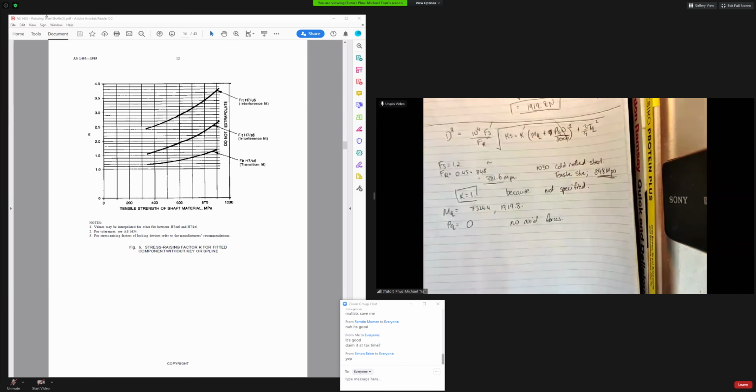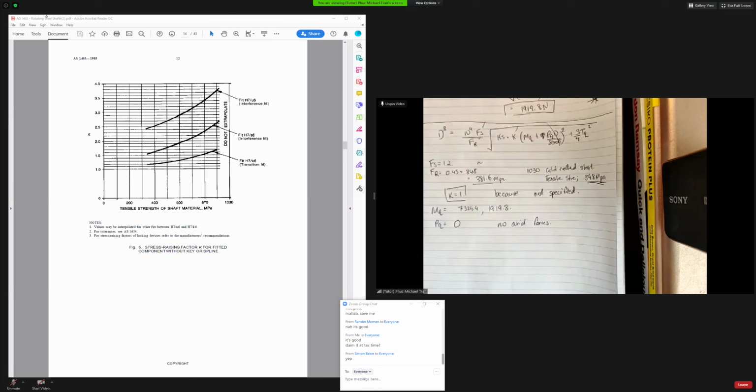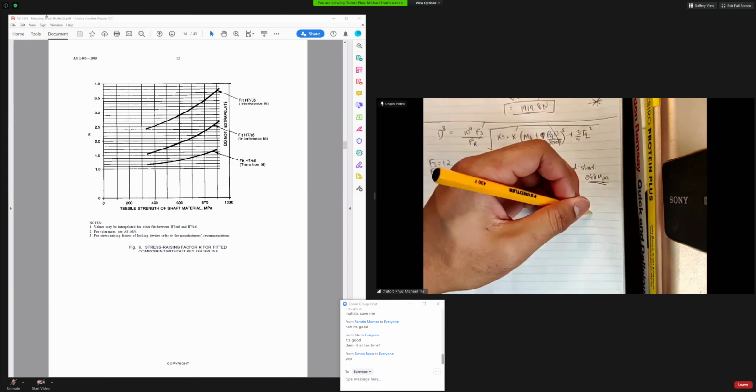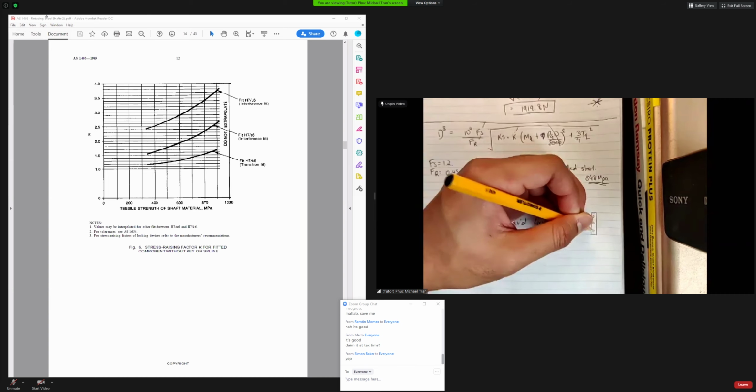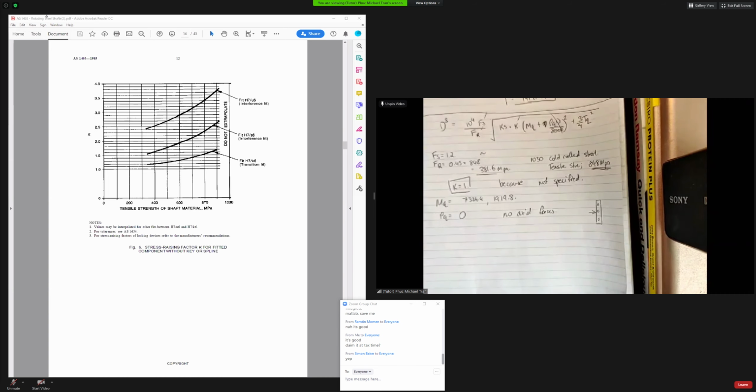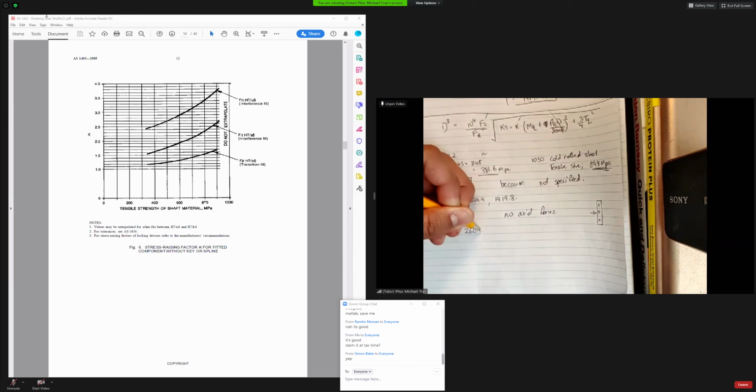You would have axial forces if you used helical gears, because there's a horizontal component to how you'd use that. Then you'd have to change your bearings to, what are they called, axial bearings, I think. The name's slipping me right now, but bearings that are allowed to take forces in the axial direction. But we don't have any in this circumstance. And TQ is 2604, and that's from the previous tutorial.